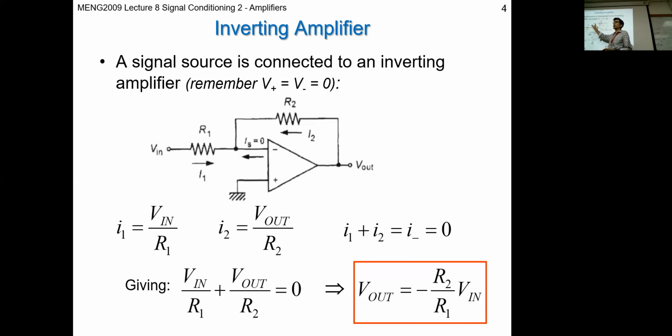So the gain of the op-amp, although the ideal op-amp has infinite gain, the practical gain of this amplification circuit is actually the negative of the ratio of R2, our feedback resistor, to R1, our input resistor. And I think last time we said as well that for an actual op-amp, we need to make these resistances pretty large.